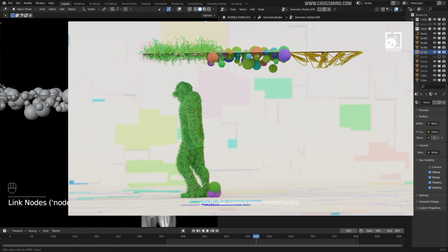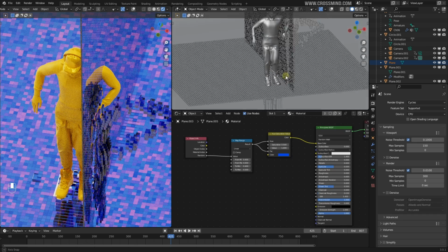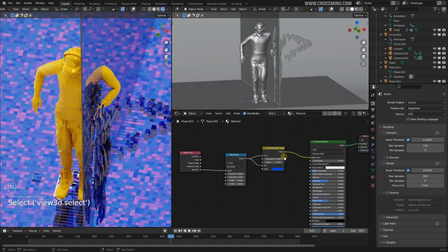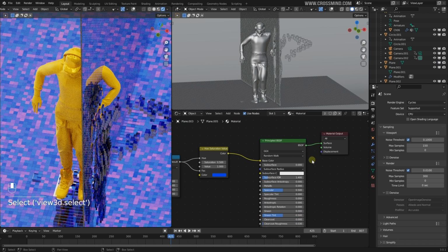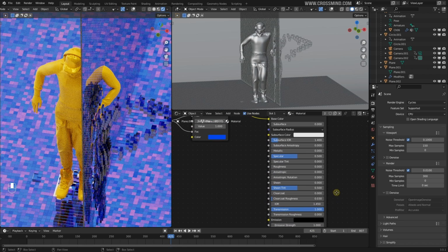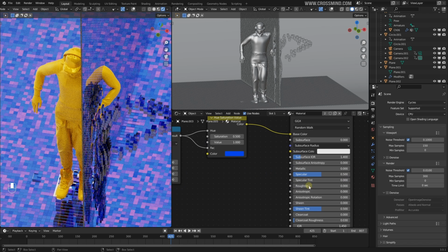And now we are going to talk about a bit of materials. So I'll start off with the very first scene. And here for the ground and all the instances I'm using a very simple setup with the principled BSDF, using the transmission, the transparency, to the max, and there is no roughness in the surface.